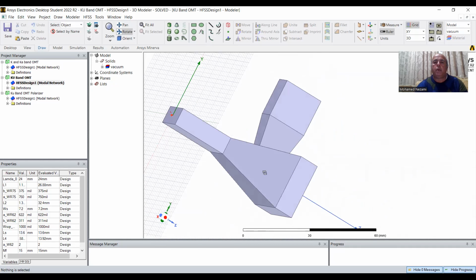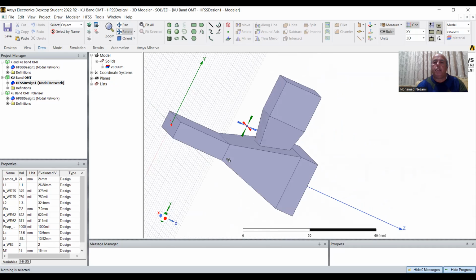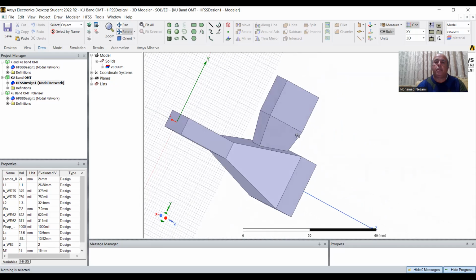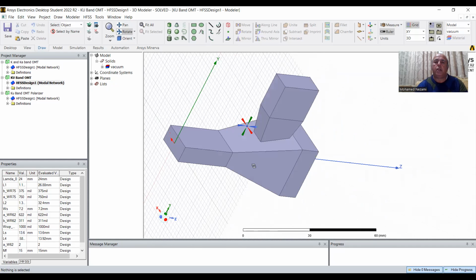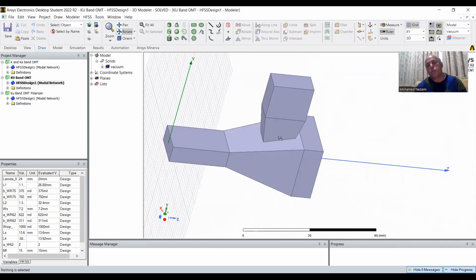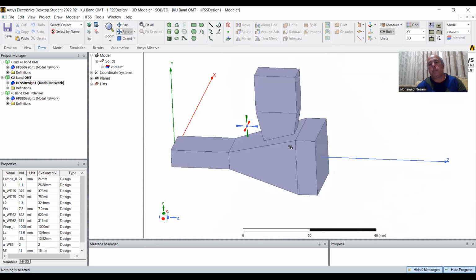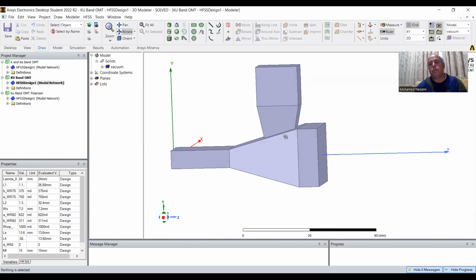It's a tapered flare waveguide, and likewise on the auxiliary branch, it's also tapered in here. And again, there is also a slot within this that couples the received signal. So we usually have the transmit side in here and the receive side on here.